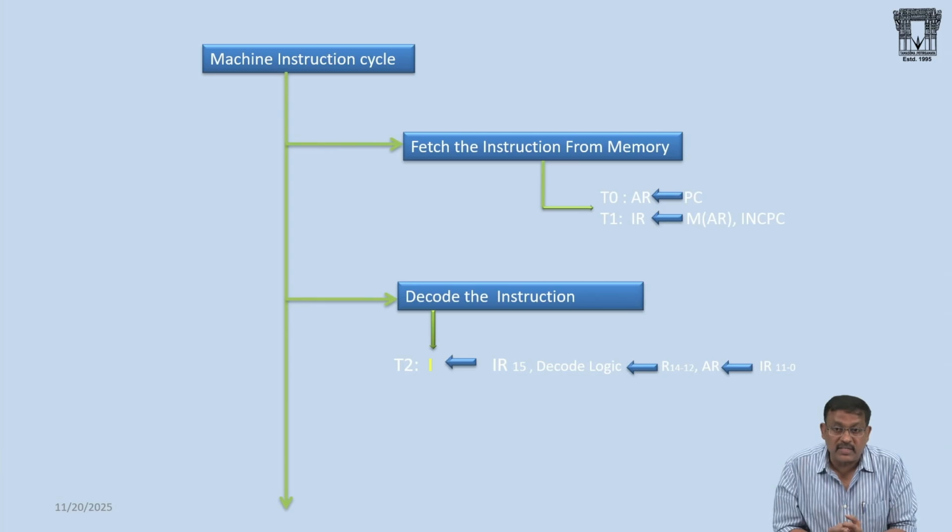In similar fashion, if IR 12, 13, 14 bits are all ones and IR 15 is equal to 1, it is not a register reference instruction. It is an IO reference instruction, right? In that case, IR 0 to 11 bits represent what type of IO reference instruction. F800, read the data, IN instruction; F840, F400, write out the instruction. Clear. See, these are all IO reference type instructions.